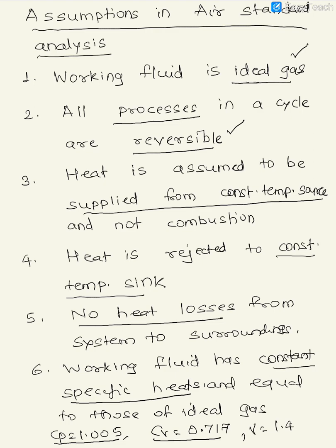All the processes are assumed to be ideal, reversible processes, and the heat is assumed to be supplied from the source and rejected to a sink, which is the reservoir, and there is no heat exchange between the system and the surroundings. The working fluid has a constant value of Cp and Cv, which does not change with respect to temperature. So all these assumptions were made.